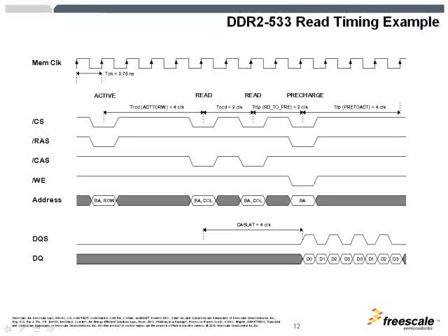After a certain number of clock cycles, which is the predefined JEDEC amount of delay between the active and read command, the read command is sent. With the read command, the column and bank information is also sent to tell the SDRAM what bank to use and what column to start sending the data from.